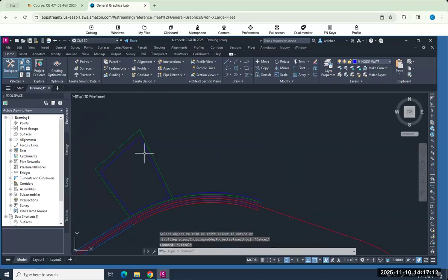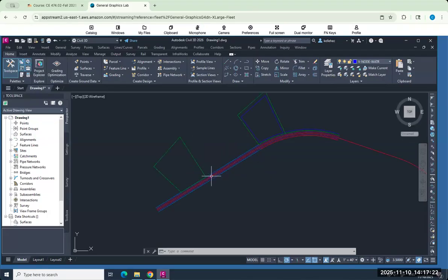So that is the way I would recommend approaching the tasks that you're doing today. Remember to use your layer properties. Remember to save early and often. I will also say, as you do this, you are going to at some point want to use the parcel creation tools. And I would say draw a couple lots and then try them out. In your memo this week, you're explaining your justification for where you're going to place certain things on your lot. And you're also explaining the process of using the parcel creation tool. It's actually pretty cool, and I think you're going to like it, but it relies on key lines.